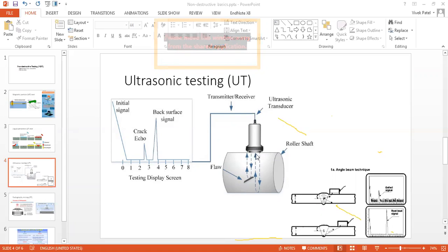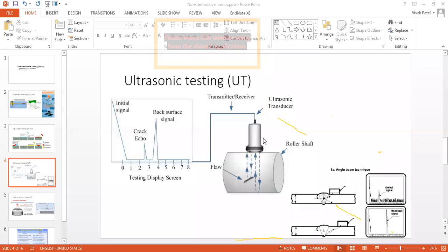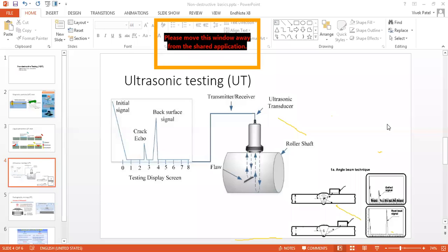And so on, you will be scanning the entire component to be tested. If I have a very large section, say 5 meter by 5 meter, then I can scan using multiple ultrasonic transducers and get information about the cross-section defect. That's why UT testing is very suitable for on-field testing. Let us take an example: gas pipelines, refinery pipelines. Once they install big diameter pipelines and do joint welding, they want to make sure whether there is a defect or not. So after welding on site, take this example of two pipes being welded.